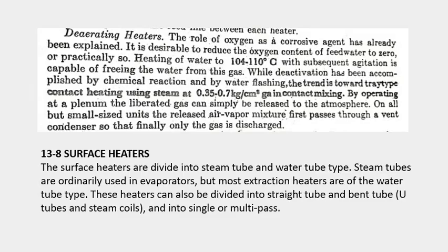And next would be the deaerating heaters. The role of oxygen as a corrosive agent has already been explained. It is desirable to reduce the oxygen content of feed water to zero or practically so. So heating of water to 104 to 110 degrees Celsius with subsequent agitation is capable of freeing the water from this gas.